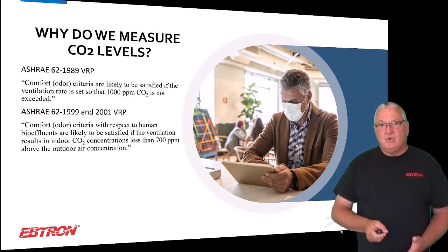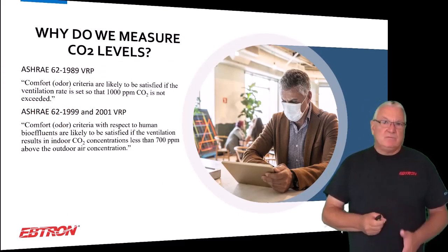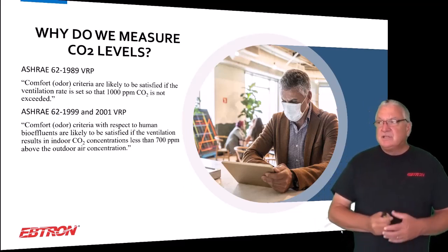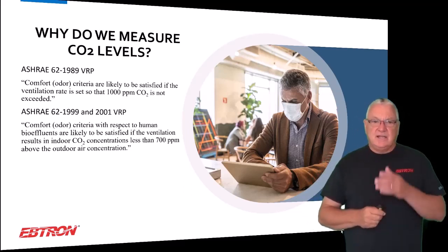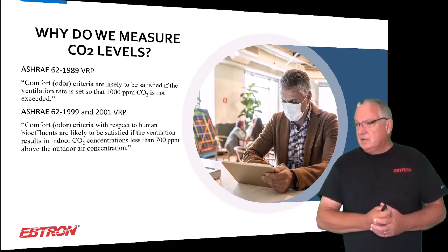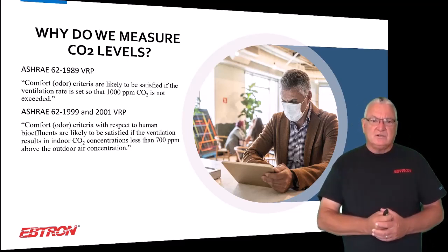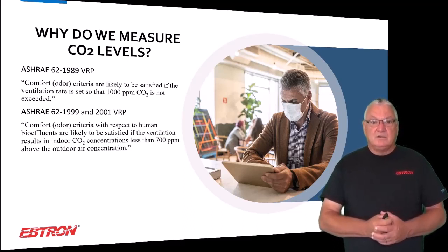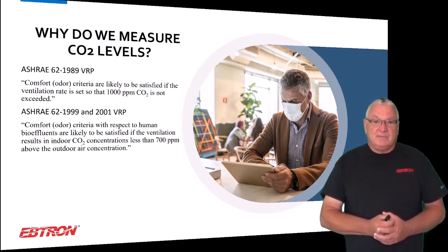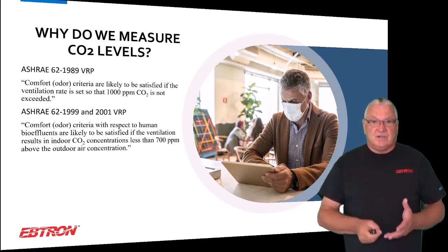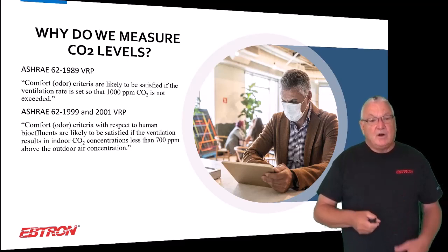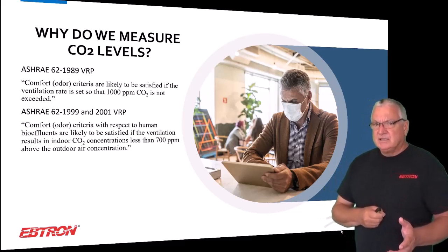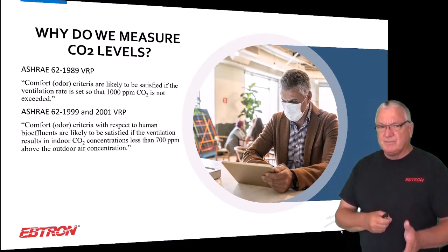What seems to be the norm, and seems to be getting more and more traction, is using CO2. But CO2 is so misunderstood. It's unbelievable to me. I've been talking about CO2 for over 30 years now, and writing about it, and basically beating my head against the wall, because folks just don't understand why they're doing this. Are you measuring CO2? Why are you doing it? Are you measuring it because it's a contaminant, or for some other reason?